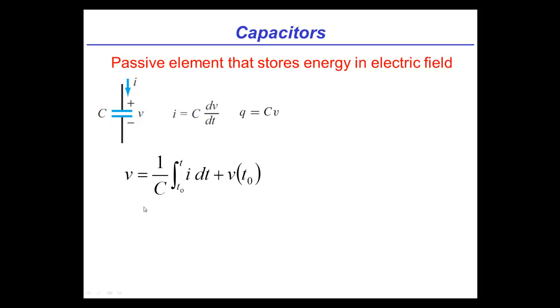Now, let's ignore the fact that we can charge up the capacitor. Let's say I've charged it up to a particular voltage. At that point, once it's charged up to a particular voltage, do you think current flows through that, Michel? No, I guess once it's held constant at some voltage. In other words, I disconnect the two nodes such that current can't flow, and it's holding its charge. It really kind of looks like an open circuit, right? There's no conductor between the two plates.